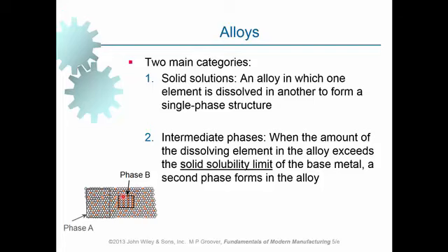Exactly. First of all, in this region, the composition of the material is different. Why is this? Because we are having a larger number of solute atoms in the material. So the composition of this region or this island will be different from the other positions in the base metal. And because of this, the resultant properties will be different. Not just that, even the crystalline structure is different.